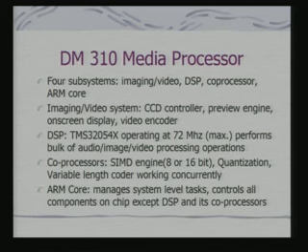Here you are talking about a CCD controller, that means you can actually control the sensor itself. So, that sensor control logic now goes into the SoC. In the case of OMAP, what is expected is that your camera is providing the data and you have got the interface to get the data. Here, how to extract the data from the CCD sensor itself and how to manage the CCD sensor, that hardware becomes part of the SoC.